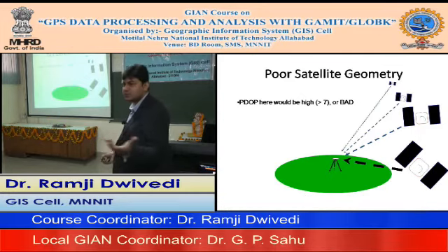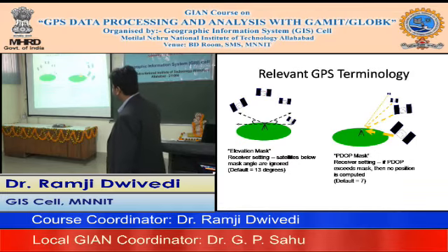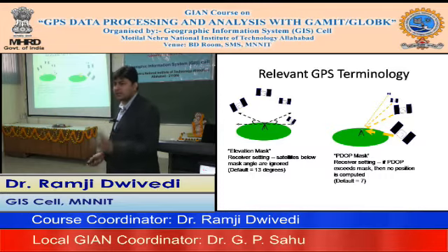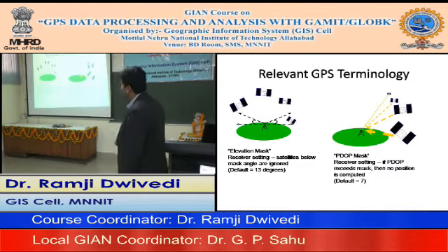And with those handheld receivers, Juno 3B or from Trimble, you could see the scatter plot. It shows very well scattered satellites, and from that you could understand that the DOP value is rising or going above. So in order to avoid poor signals, you could also relate it to the phase residual map from that GAMIT session, where from 0 to 10 degrees you don't have any map; it starts from 10 degrees. Similarly, you don't want to use signals from these particular zones, so that when a satellite comes up and reaches a particular geometry, only then you read the data set.